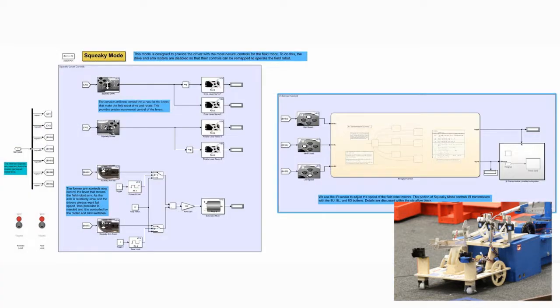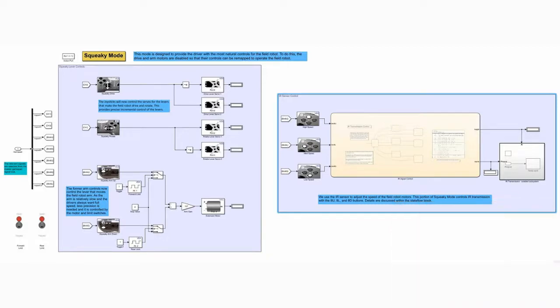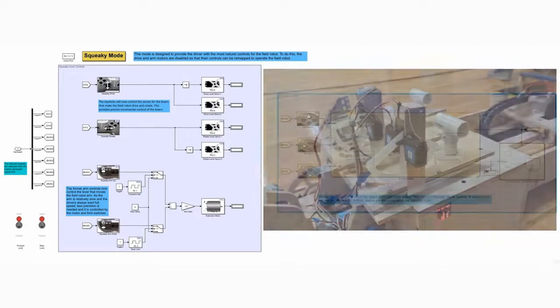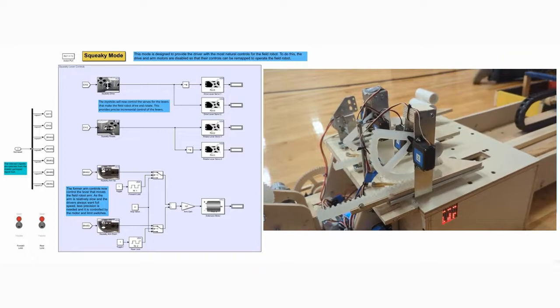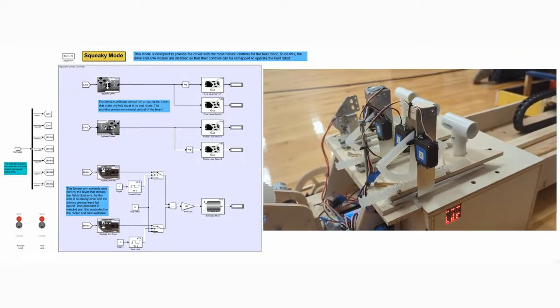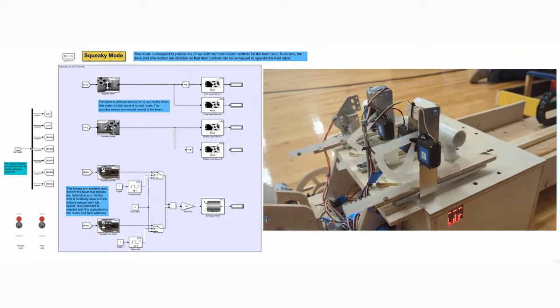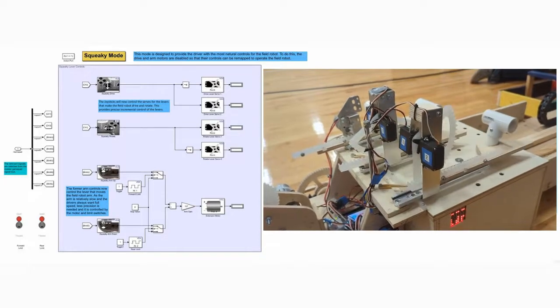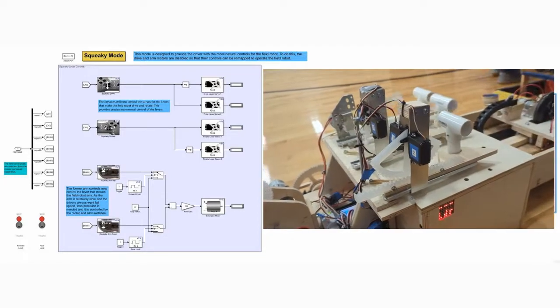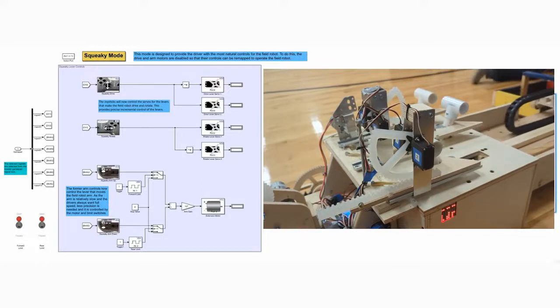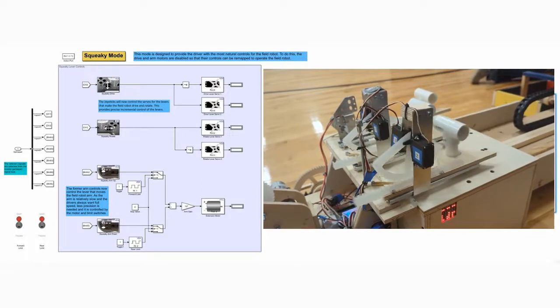Squeaky mode is engaged once the robot has been aligned to the field control box. In squeaky mode, all drive and arm motors are disabled and the controls are remapped so that the joysticks and digital buttons control the lever manipulators that control squeaky. In this way, the drivers don't have to focus on moving a particular lever. They can simply consider the controller to be operating squeaky directly.